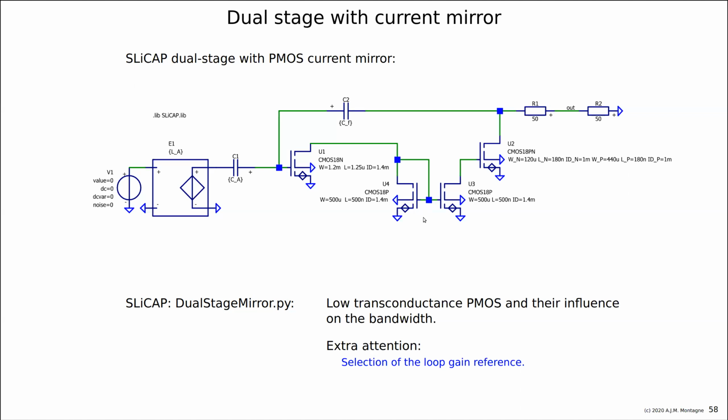So what we could do is just remove the capacitor from the first transistor, take our loop gain reference there, and then replace it, but then only studying the change in the gain by placing it or leaving it out. If there's no significant change, then the feedback capacitance doesn't play a role. Then there's almost no Miller effect in the stage. And that's what I want to demonstrate as well for this design.